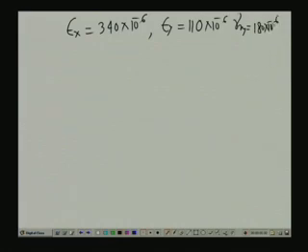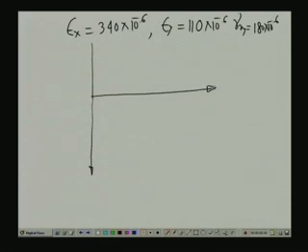Now, if we plot this in the Mohr-Circle, let us say this is the gamma by 2 direction, this is epsilon direction, this is gamma by 2 direction. Here we have epsilon x 340 and gamma by 2 is 90. So, this is the point which we choose here. We have another point epsilon y which is 110 and gamma by 2 is minus 90. So, we place the point here, and as per the norm of the Mohr-Circle, we join these 2 points,